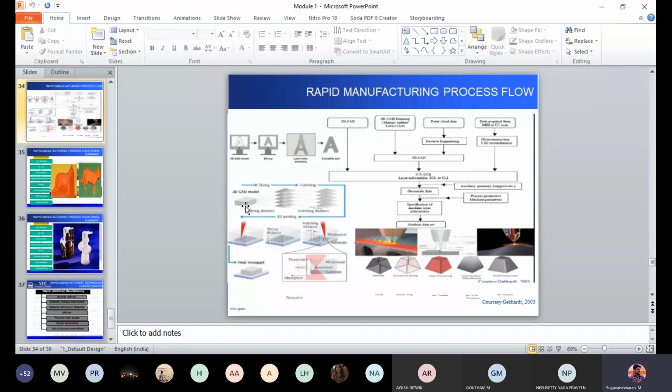That is, virtually you have to cut a part with a plane parallel to XY plane and make sure that between each cut the distance is 0.5 mm. So you will get 20 contour information. So that procedure is called slicing. So that is the next procedure in additive manufacturing. Once you create a slice, for each slice you have to create a tool path. So you require a proper tool path for each slice.